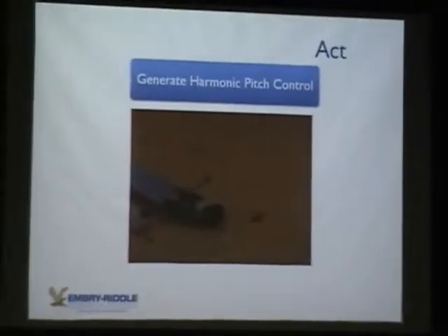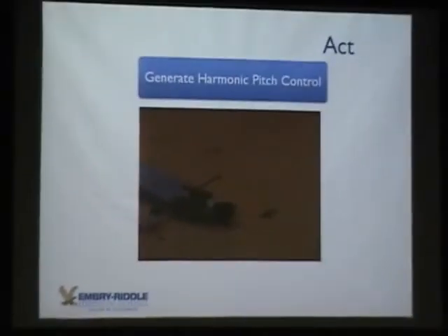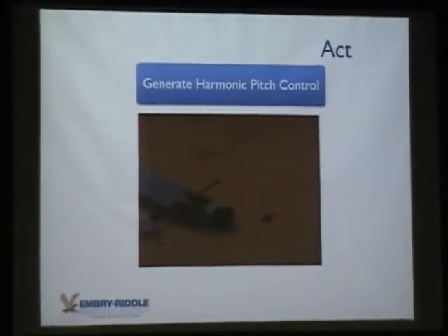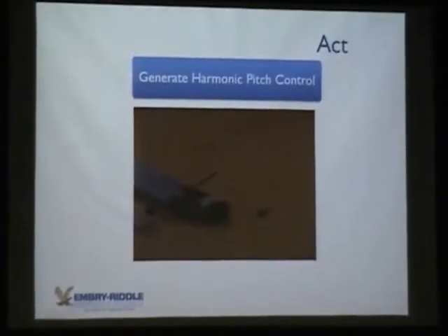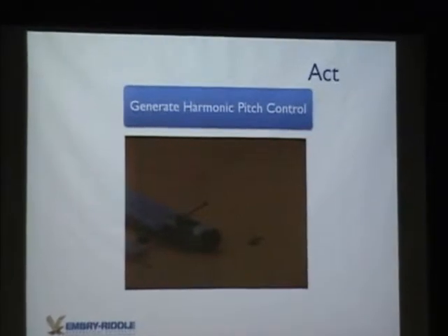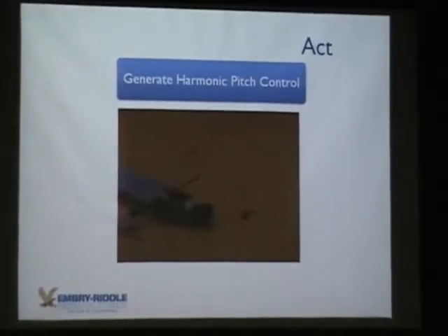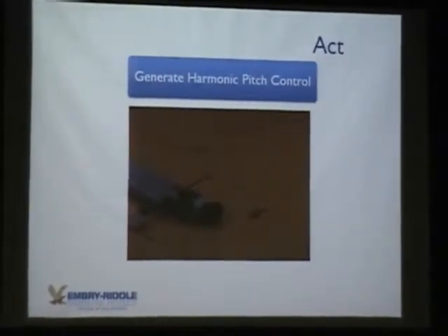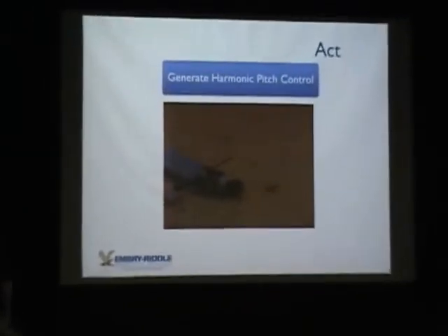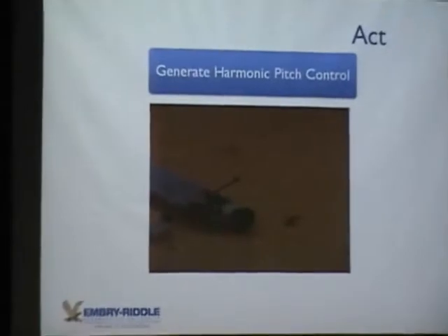As the vehicle's rotating, we have inherent self-stability. When the vehicle takes off, if nothing's moving, the natural trim of the vehicle is for it to sit and hover. The flap is a Hiller-type flap. If we move that flap harmonically, taking multiple positions within one rotation, we can actually tilt the axis of rotation and get lateral motion in a controlled fashion. So that's what we do.